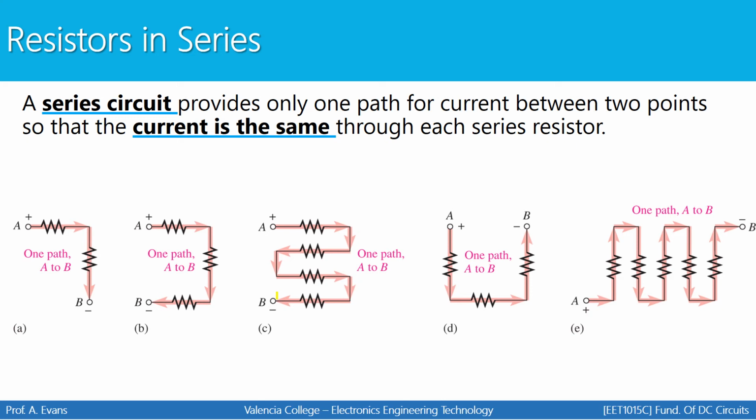Even though if you were to think about this on a geometric type of basis, these resistors are parallel to each other. If we think about how they're laid out in terms of how we visually look at them, we can make the argument in a geometry setting that these resistors lie on parallel lines. But that's not the definition within a DC circuits class we will use to define whether something is in series or in parallel.